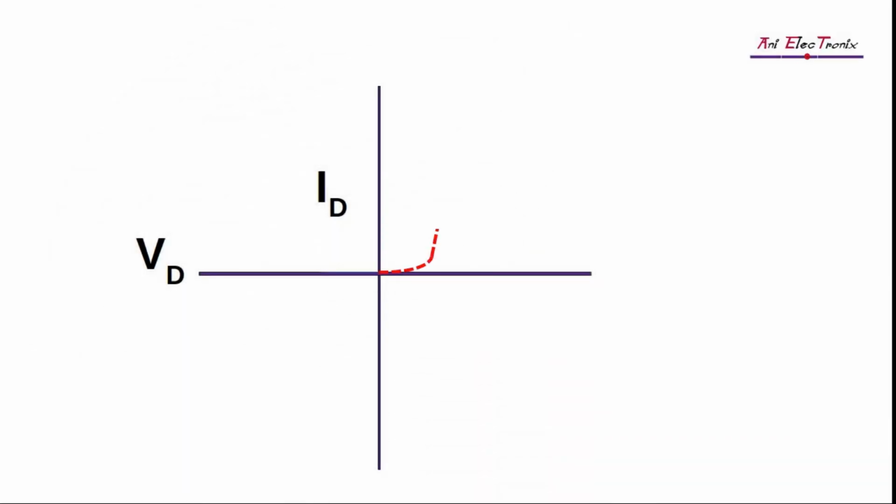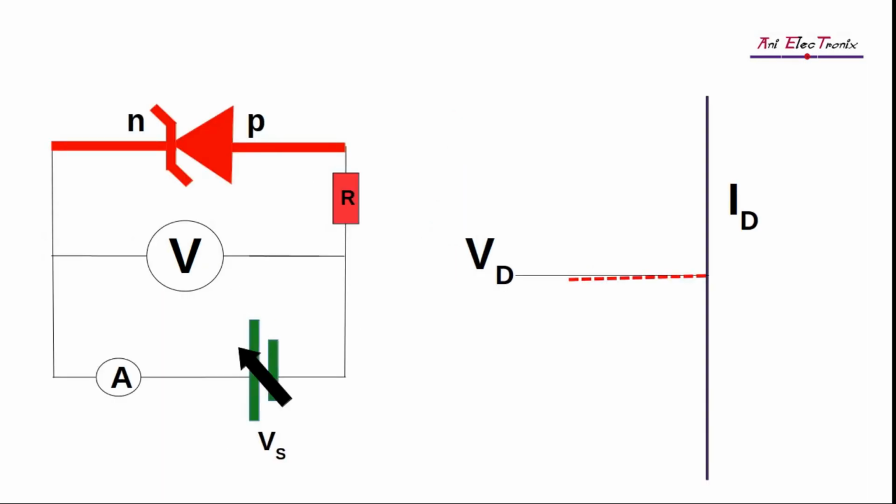Zener diodes can operate with ease in 3 regions: forward, leakage, and breakdown. In the forward region, after crossing the knee voltage, which for a silicon diode is 0.7 V, the diode can start conducting. The Zener diode maintains a constant output voltage regardless of the current through it. For this to occur, the source voltage must exceed the breakdown voltage of the Zener. The current passing through the Zener diode should be less than the maximum allowable current set by the manufacturer. As a result, a series resistor is always used to protect the Zener diode.